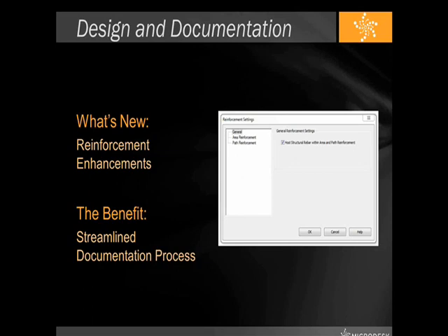Each is created using the same sketch editors, and the symbols and tags remain the same. However, the main difference is that structural rebar elements will now appear in the floor or wall and can now be properly scheduled. Rebar sets will be created when possible, and individual bars will be created when sets cannot be defined, for example, along an arc.